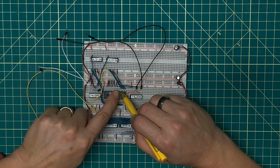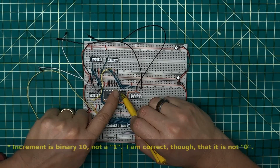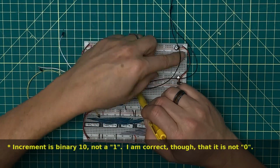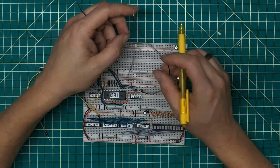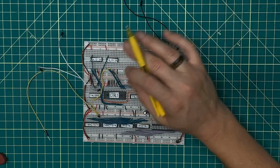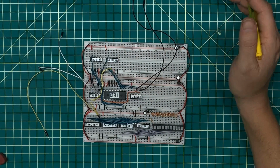I have bit 6 and bit 7 here of the control byte are set to be the load, increment, and decrement for the program counter. Now increment is 01, so the low bit here needs to be a 0. The high bit here needs to be a 1, so that is something that's not going to be 0. But it will allow me to have all the control signals I need in order to execute a no-op instruction.